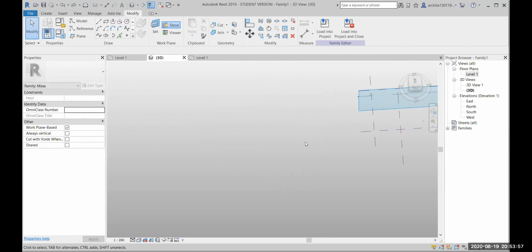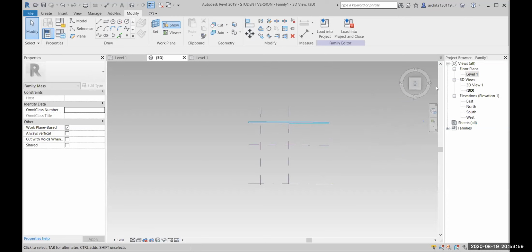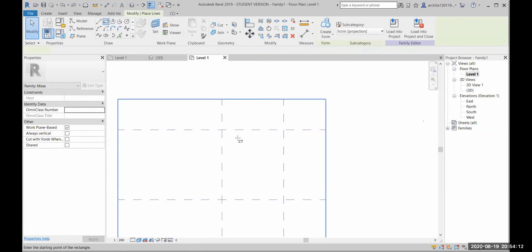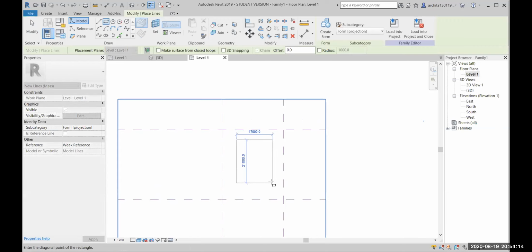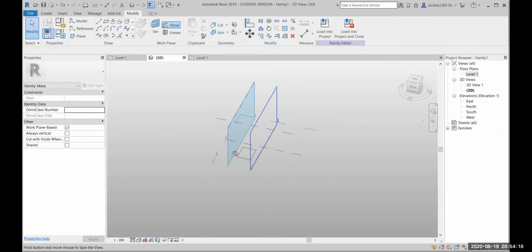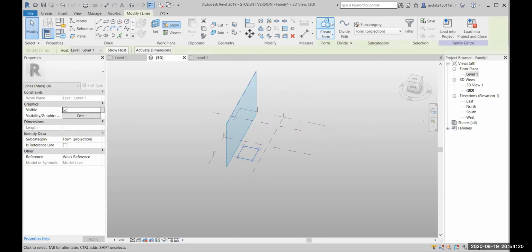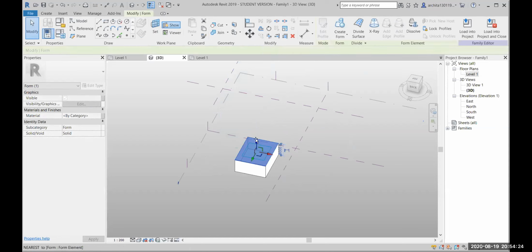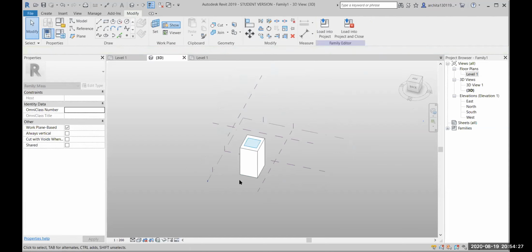See, this much you know that we have created extra planes. Planes, you know now how we created the planes. Planes I know. In the floor plan only we need to create, or in the 3D view? See, it's better that in floor plan you go and just draw the rectangle. That's it. And then in 3D you go and click on the rectangle and do create form. That's all. Okay, here there are two reference lines, ma'am. Top and then bottom.